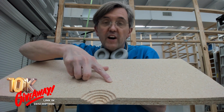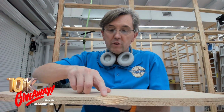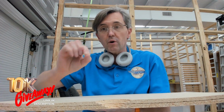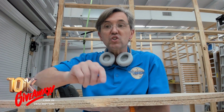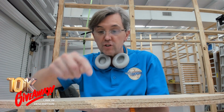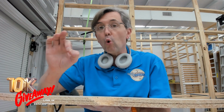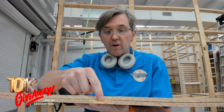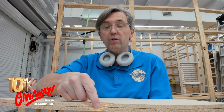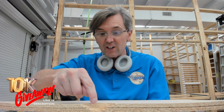The vectors were just simple circles, and they were pocketing toolpaths, where with the first one, it was start depth 0, cut depth 1/8 of an inch. The second one was start depth 1/8 of an inch, the cut depth was 1/8 of an inch. The third, the start depth is 1/4 inch with a 1/8 of an inch cut depth. The fourth was a 1/2 inch start depth with a 1/8 of an inch, and so on.